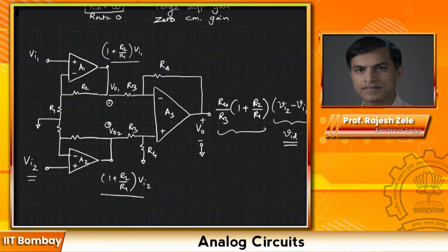And so the positive about this, as I said already, is since there are two cascaded amplifiers, that would lead you to large gain, which we desire. Also, another positive is Rin is equal to infinity, because you are going into an op amp, you are looking inside the op amp terminal.